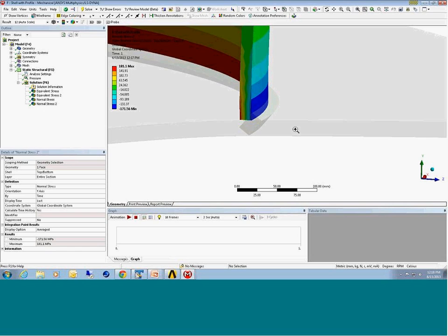One of the things that's sometimes done to calibrate that and to get a consistent result is maybe making the mesh size such that the end element is about the thickness of the weld. So I've seen people do that and pull centroidal data as well. So there's a variety of different ways to extract that data.